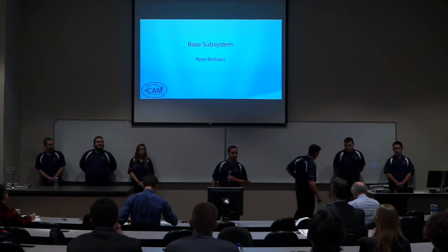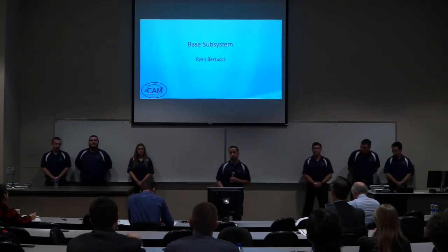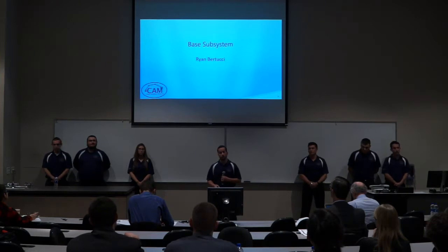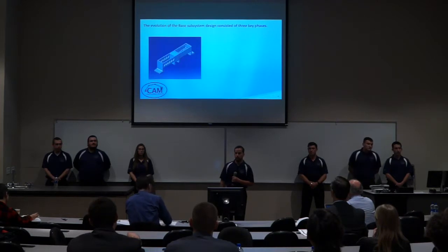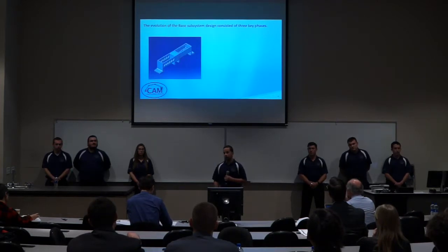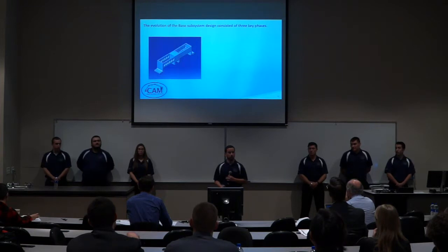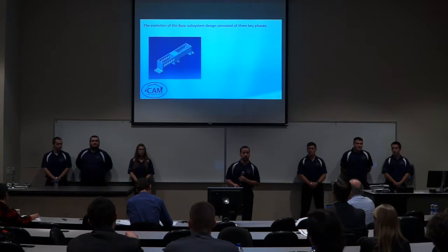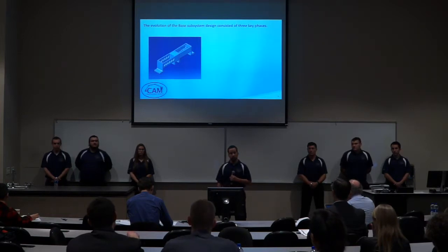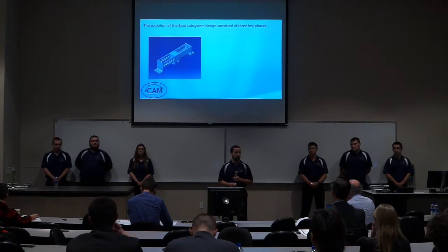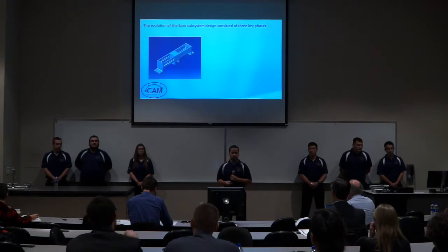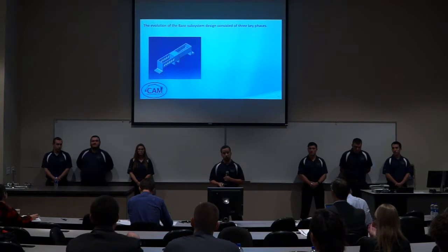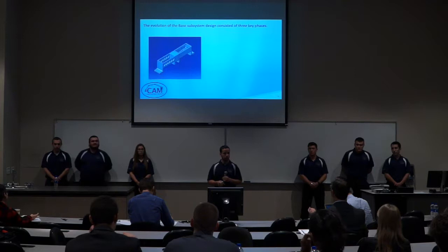All right, thank you, Aiden. Going into the base subsystem, the base is going to be the primary means of attaching the overall system to the ISS, which is in direct fulfillment of our primary mission objective. The evolution of the base design was spurred basically off of our secondary mission objective of wanting to attach to all three interfaces. Our initial design went off of our trade studies, in that we wanted to keep the design as simple as possible, keep it manually powered. With this design, we had minimal moving parts. It was spring operated.